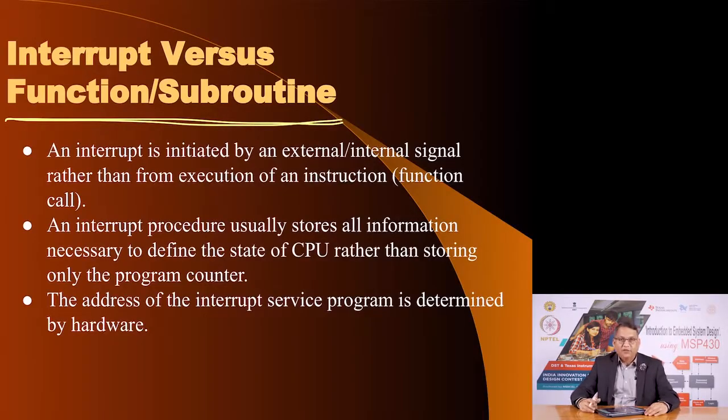In a normal function or subroutine, you call that function, but in an interrupt you do not call the interrupt subroutine, the interrupt subroutine gets called. Why? Because it is often the result of an asynchronous operation, like a user pressing a switch.